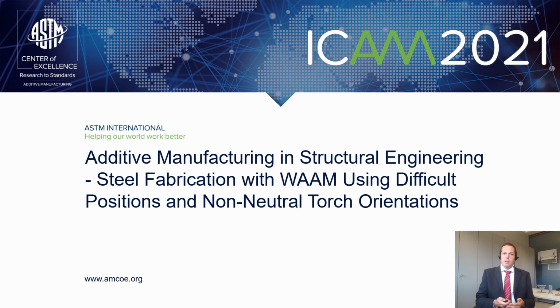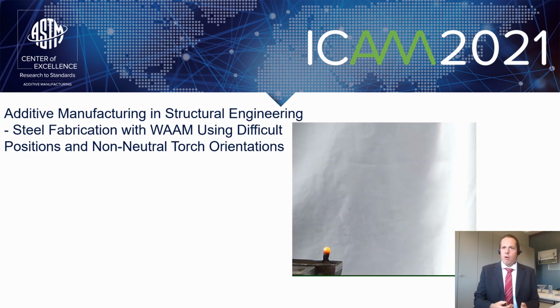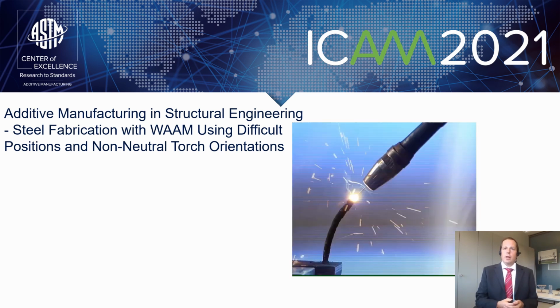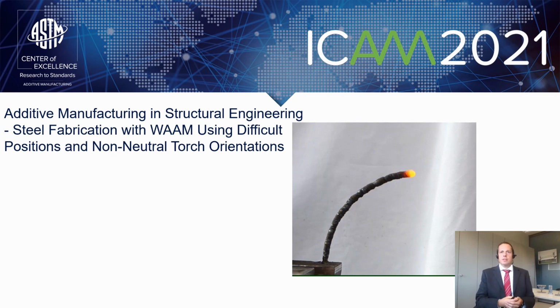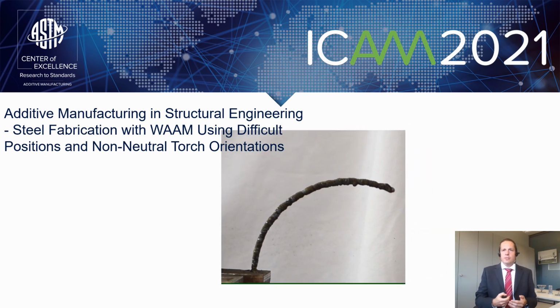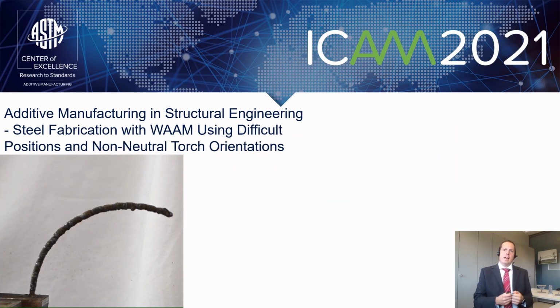Now you can see a time-lapse video of how an arc is made using the type of additive manufacturing we use. The WAAM method is called Wire Arc Additive Manufacturing. I will explain this method in a bit, but what I want you to know now is that it's based on welding and the arc consists of punctual welds. As you can see, it's possible to print mid-air, but also the quality or the geometric stability of the welds get worse the more we print sideways.